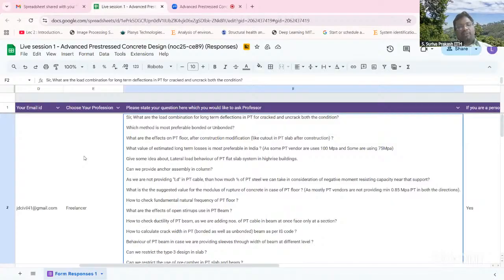Obviously, that's true. Just adjacent to your pre-stressing anchor location, there will be a region that will not see the effect of pre-stress. So those locations you have to design carefully.